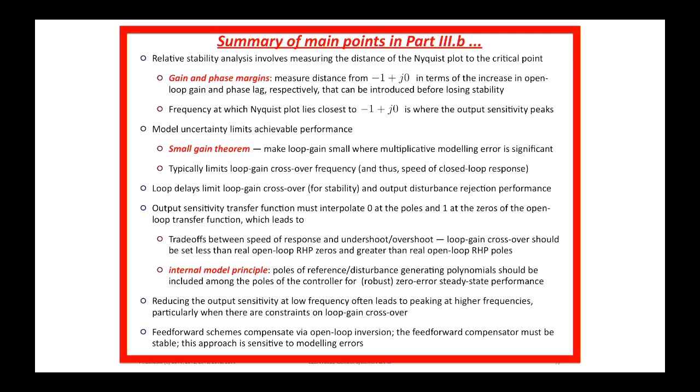And we've just seen how to incorporate an additional degree of freedom to help you in situations where you can't separate the competing objectives into different frequency bands. Okay, but you've got to be careful because the feed forward part here is like open loop control. And open loop control can be sensitive to modelling errors. All right, so tomorrow we'll start looking at part 4 of the notes, which is really about design. We've done a lot of analysis now. We're going to start, we've done some design. Now we're really going to look at design. And then on Friday, we'll look at problem set 4.